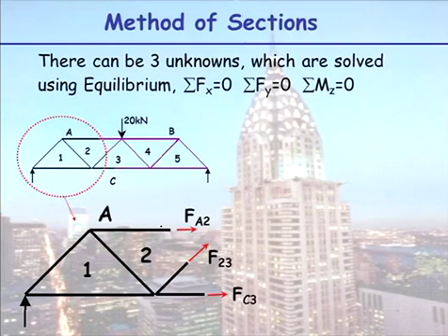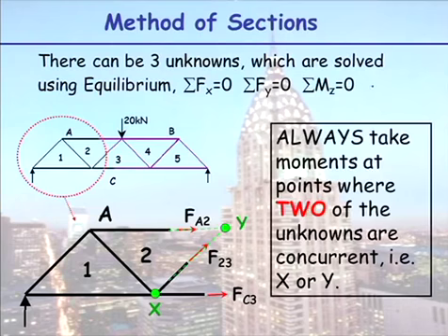So with the method of sections, you cut through the section, and when you do, because it's a truss, typically you cut through three members, and we have three equations of equilibrium. We can use our moment equation this time because all our forces aren't concurrent. You can't trace all these forces, the forces I'm talking about being our reaction force here and these unknown forces, back to one point. So we can utilise our third equilibrium equation, the moment equation. Now the thing with the method of sections, I just so dislike when I hear I get the method of joints, I just don't get the method of sections. The method of sections is just equilibrium. That's all it is. So there's nothing not to get.